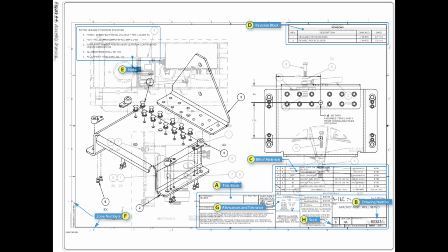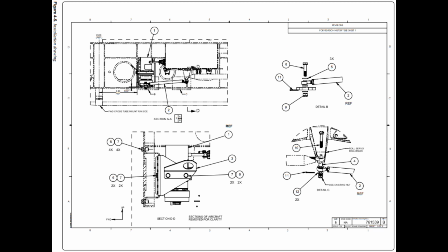Installation drawing. An installation drawing is one that includes all necessary information for a part or an assembly in the final installed position in the aircraft. It shows the dimensions necessary for the location of specific parts with relation to the other parts and reference dimensions that are helpful in later work in the shop. Figure 4.5.